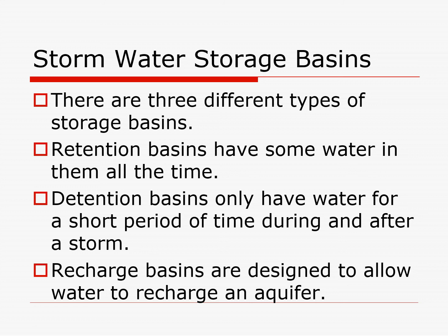Detention basins only have water for a short period of time. Like I said, you'll also see those, and they generally will be empty unless it's raining, and then they'll be full or have some water in them depending on the storm. And the recharge basins are designed to hold water, but instead of letting it go out into the stormwater system, it goes back into the ground to recharge an aquifer.